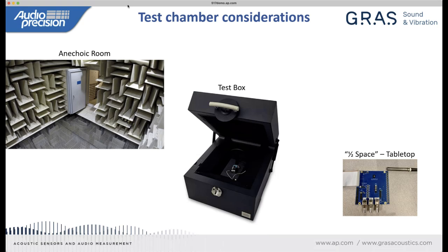What's going to happen here is you will get a reflection off the surface, but because everything is sitting on that surface, that reflection is coincident or simultaneous with our test signal and just expresses itself as a doubling of the effective sound pressure level from my source speaker, which is actually, in the case of measuring a microphone, quite convenient.